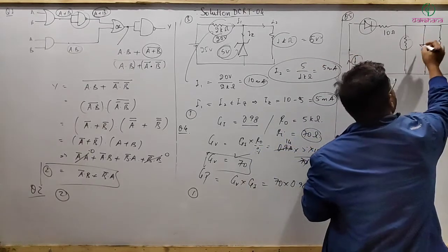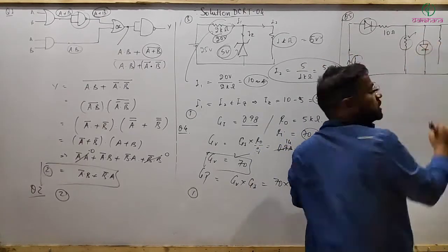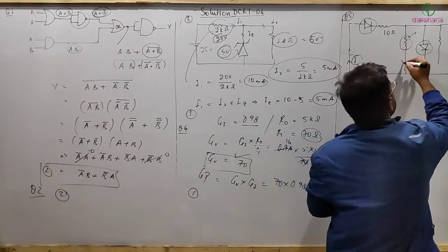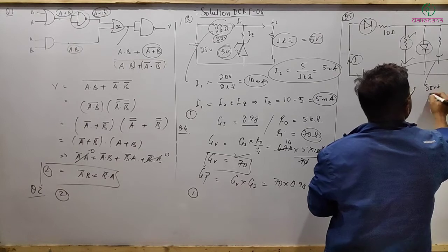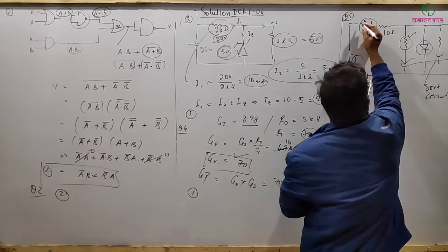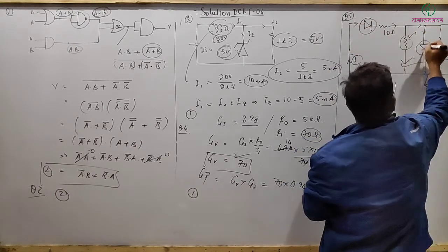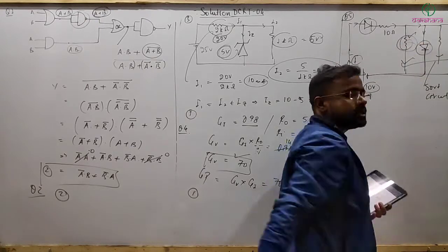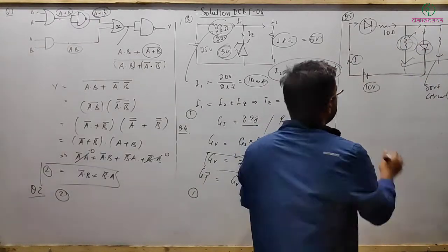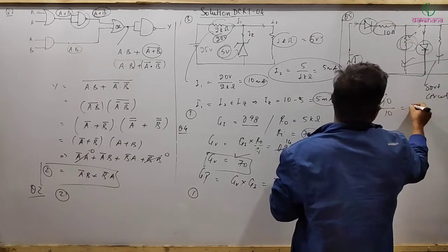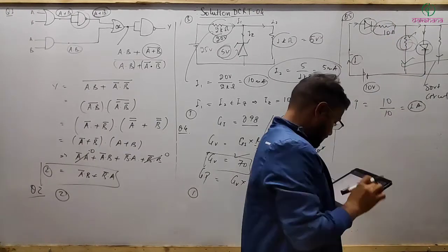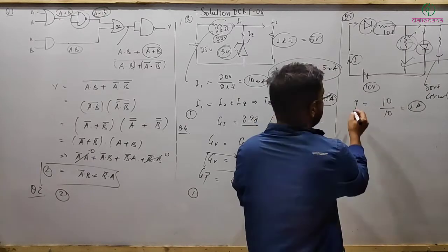तो अभी यहाँ पे क्या होगा देखो, एक तो ये कुछ resistance और here it's 0 resistance. So what it means is all these are short circuited. तो इसका मतलब क्या होगा, टोटल करंट यहाँ से और फिर यहाँ से पास कर जाएगा. So it means these resistances are not active. So then current can be simply given by 10 volt divided by the only resistance, 10, which will be equal to 1 ampere, and that's matching with option number 3.